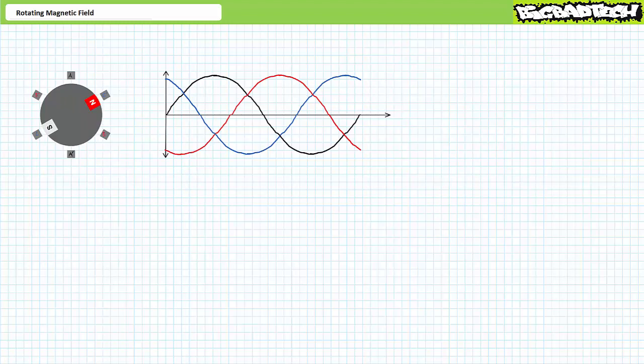Consider a 3-phase AC stator winding consisting of 6 individual poles, 2 of which are energized by phase L1, 2 of which are energized by phase L2, and 2 of which are energized by phase L3. This 6-pole stator has 2 poles per phase. Given poles never appear in isolation, but only with their opposite in tow, it can also be said that this is a single pole pair per phase motor.